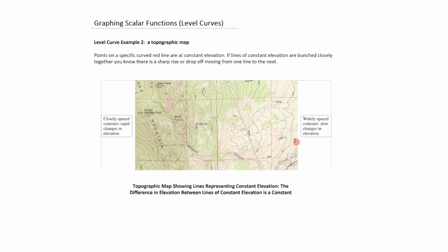And if you were to look at a river valley, without knowing the elevation values, you could basically see that when you see a lot of lines in parallel on one side and a lot of lines, not necessarily parallel, but very, very compressed on the other side, that tells you you're in a valley. You're going down one side and you're going up the other side. So it's very useful to get a projection of a 3D object onto a plane. All right, so that's something very useful in terms of how it's applied in the outside world.